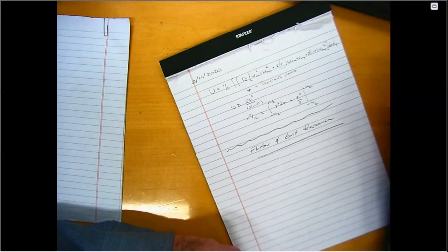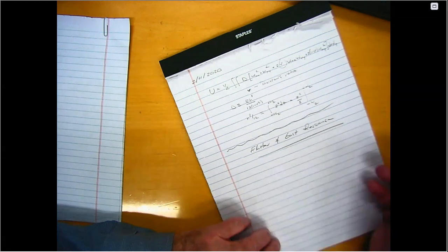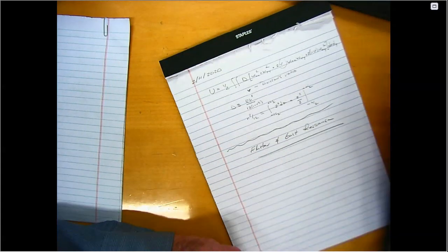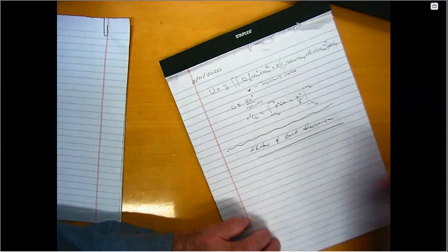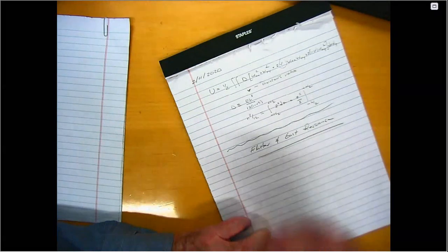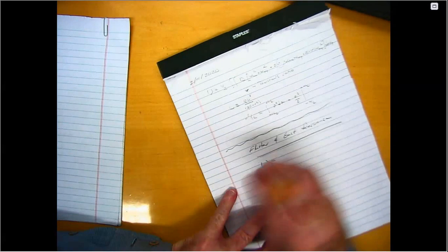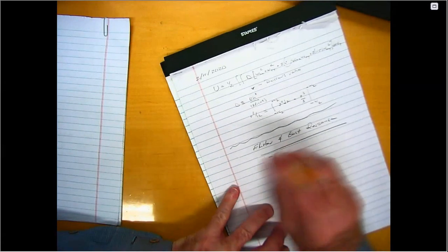To illustrate what can happen dynamically, I'm going to start with the simplest possible model. Namely, again, just our torsional model, except we're going to add dynamics, which means we're going to add kinetic energy. So now we're going to have some additional terms in our equations of motion. So let's see. Let's go back to our typical section model. Let me draw a picture so you know what I have in mind.